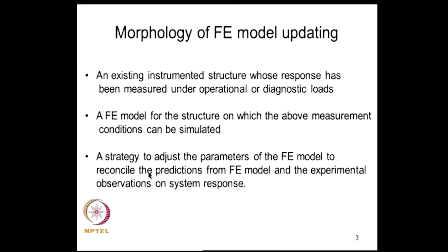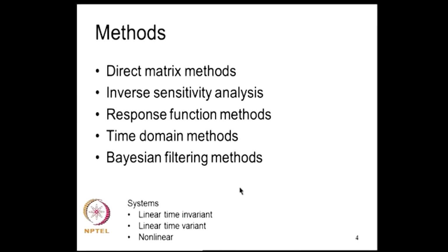Then we need a strategy to adjust the parameters of the FE model to reconcile the prediction from the FE model and the experimental observations on the system response. Here we should take into account features like mismatch of degrees of freedom between the finite element model and the experimental model, presence of noise in sensors in experimental work as well as imperfections in the finite element model, and so on and so forth.